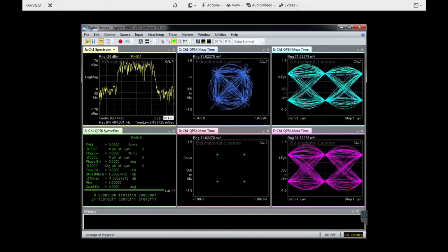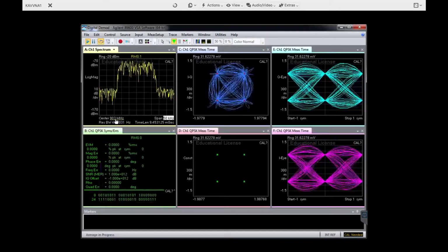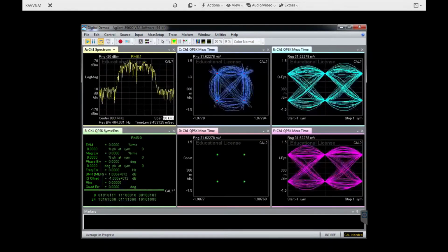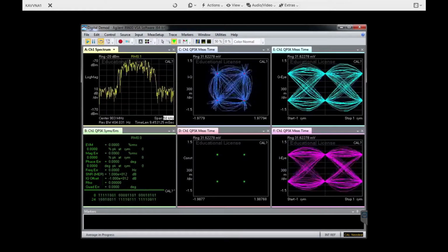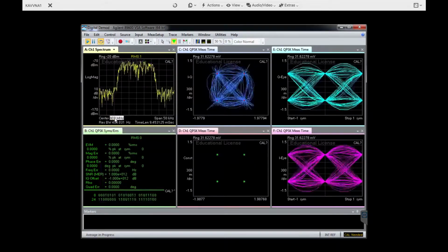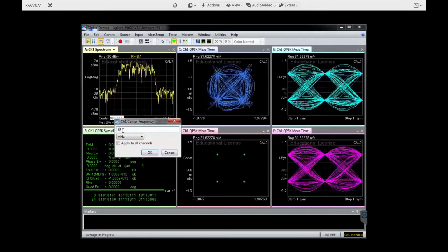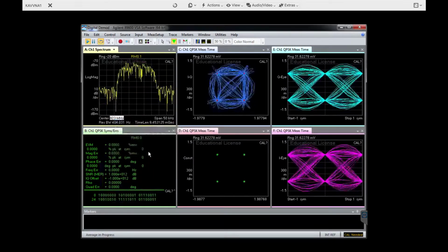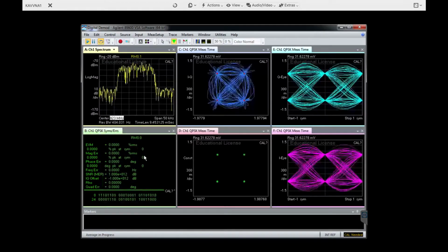So you can see this is the signal that we are receiving at 903, which is the harmonic produced by the mixer, and it exactly contains the signal that we are transmitting. As you can see, the demodulation is perfect. Again, we can also observe the same thing from the harmonic at 923 megahertz. Again, we are receiving what we are expecting.